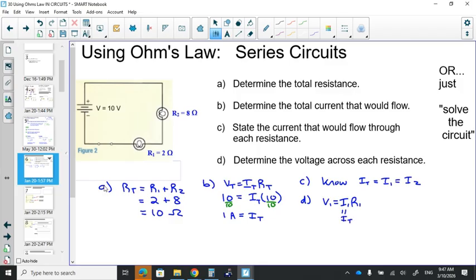Anyways, total current, right? So our equation becomes E1 equals total current times R1. You don't have to write that in, but your next line certainly would be having that value in, the 1 amp, if you didn't show it specifically. Maybe you just do this, where it's equal to total current, as a way to communicate what you've done. And then your next line can just be the 1 plugged in, and then the 10 for the resistance. And so you'd get, on this one, resistance number 1 is just 2, and so we'd have 2 volts dropped on that first one.